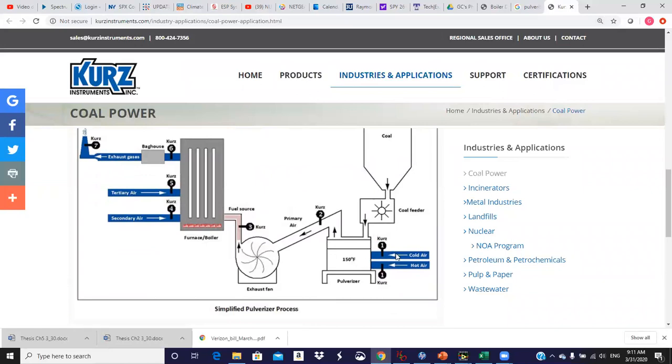And we have a cold air feed and a hot air feed. The hot air would be air that has gone through the air preheater, and they are blended to maintain the desired temperature of the air and the flow through the pulverizer. Then this is showing an exhauster fan, which exhausts the pulverizer, which then goes through the coal pipes into the burners.